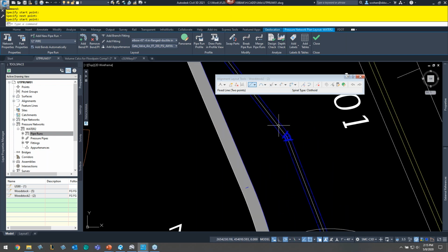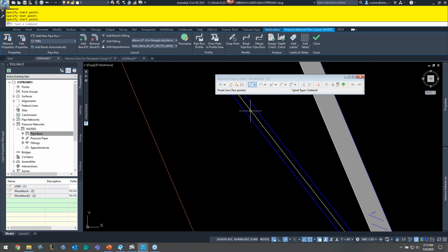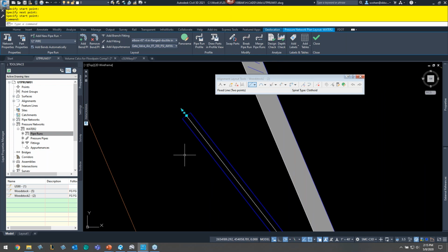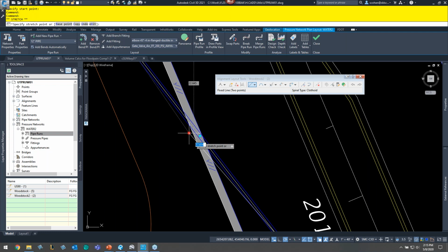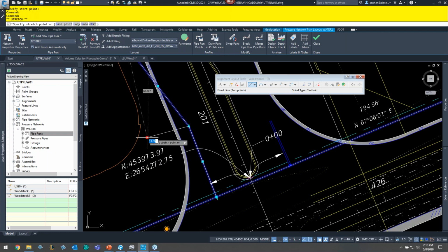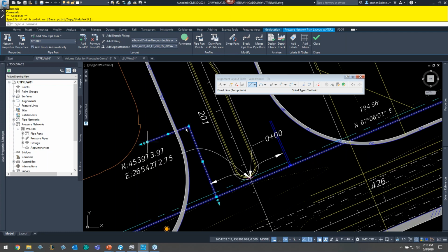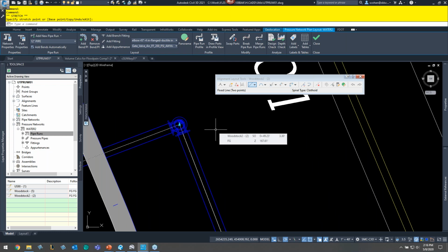And the other really cool thing that is done here is if I go ahead and select that, and then I go ahead and modify this here. Let's go as close to perpendicular as I possibly can. It's supposed to, let's see if it does it. It's supposed to update, and it did. It updates the actual fitting. I mean, everyone who does pressure networks should be jumping for joy right now, which I am, because I've done a couple of water sewer projects, and I actually went to core models because this, you couldn't do, I had to update it constantly.